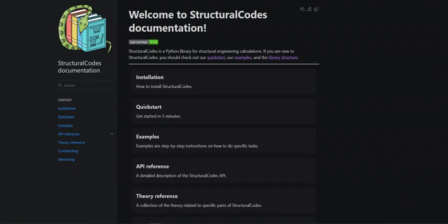Well, we already covered the bending strength, but you also have the limit axial load. So that would be the maximum tensile and the compressive axial load you can put on it. You also have interaction domains. So both pure biaxial bending for a given axial force. You have the interaction domain for one axial force and one moment, and also a 3-dimensional space where you have biaxial bending and axial force.